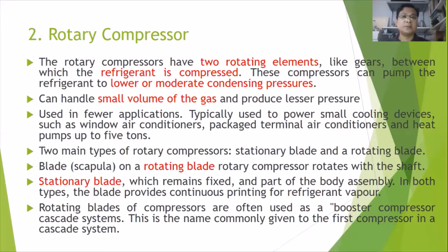Second, it can handle a small volume of gas and produce lesser pressure, so maybe this one is very useful in small hatchback systems. Third, it is used in fewer applications, typically to power small cooling devices such as window air conditioner, package terminal air conditioner, and heat pump of 5 tons.